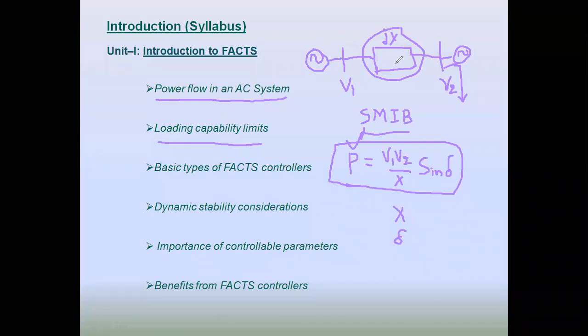Apparent power or even real power limit also we can consider. A kVA limit will be there generally for any transmission line. So generally that limit, that capacity of the transmission line, depends on three factors. One is thermal capacity, thermal conditions. Second one is dielectric capacity or the voltage limits. Third one is the stability considerations.